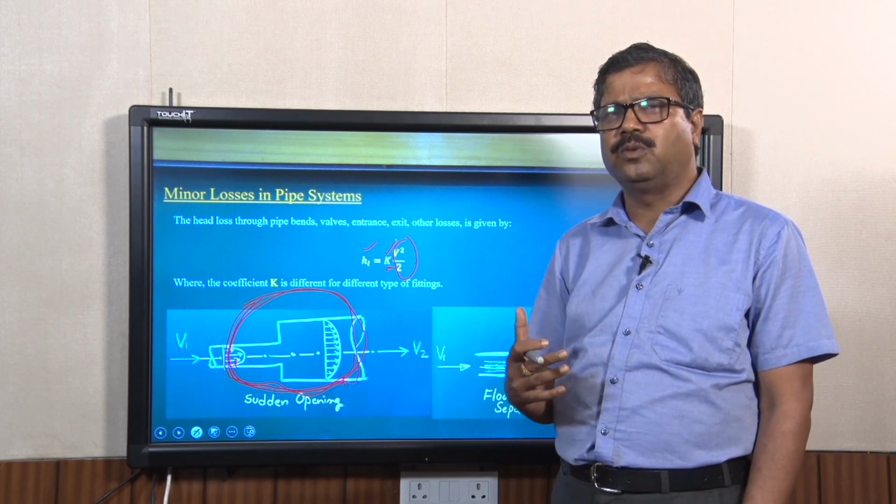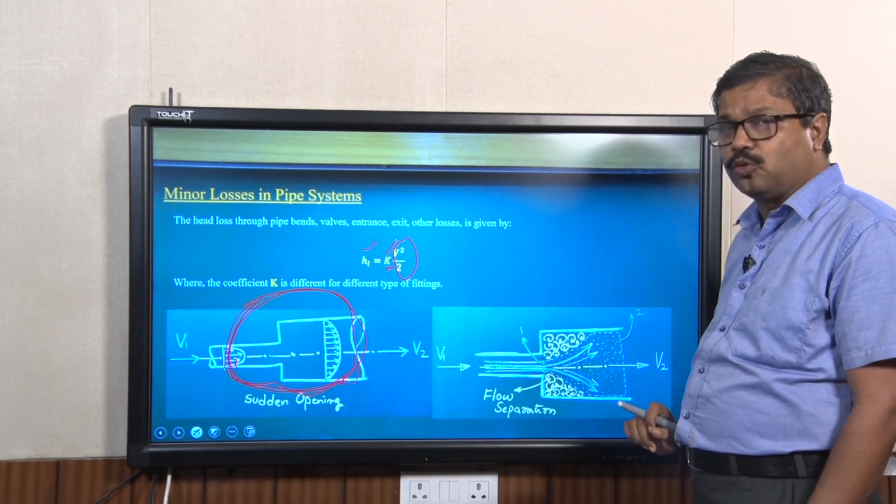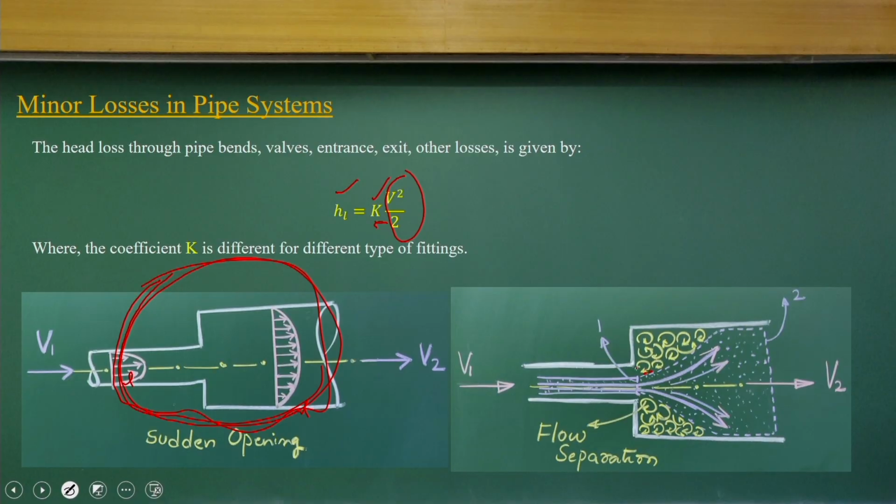But from your point of view, I am just explaining how the flow process happens within the pipes. Now let us look at how it happens. Again I am considering virtual fluid balls. The balls which go very close to the wall will go straight and inject here as tangential and go like this. What will happen to this? Here also you have the liquid, but that liquid will have a vortex formation. They will start rotating. So majorly your flow passing these regions will have vortex formations.